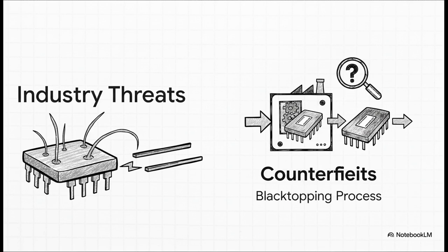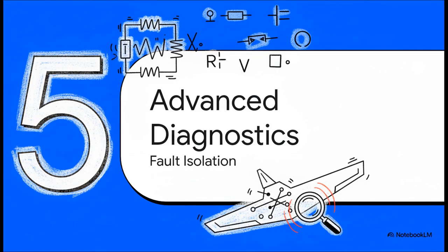Beyond those standard failures, two industry-specific threats are everywhere. First, tin whiskers. These are microscopic, conductive filaments that literally grow from the pure tin plating that was mandated by RoHS directives, and they cause shorts. This is mitigated in aerospace by exemptions for using tin-lead solder. Second is the problem of counterfeit components, which is governed by the AS6081 standard. Component obsolescence forces procurement into gray markets, where old parts are harvested, remarked, and sold as new, a critical threat to system integrity.